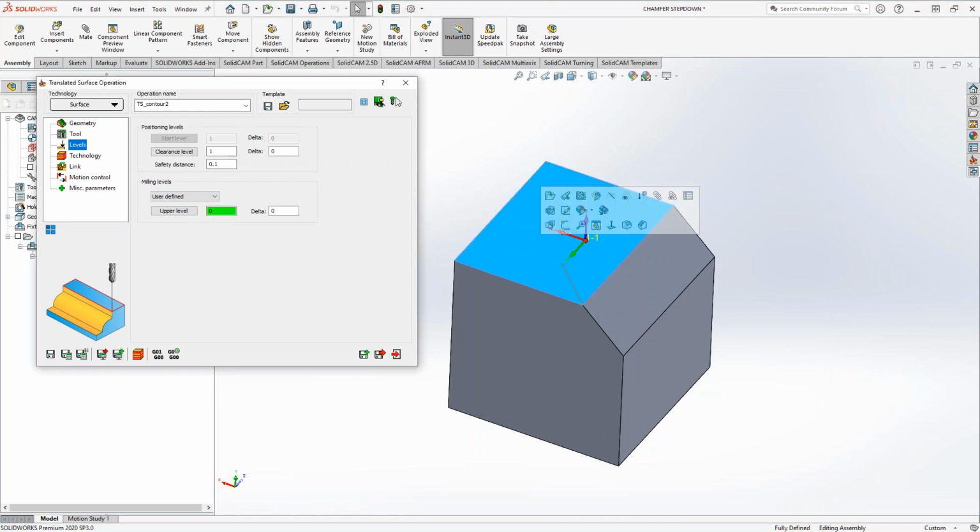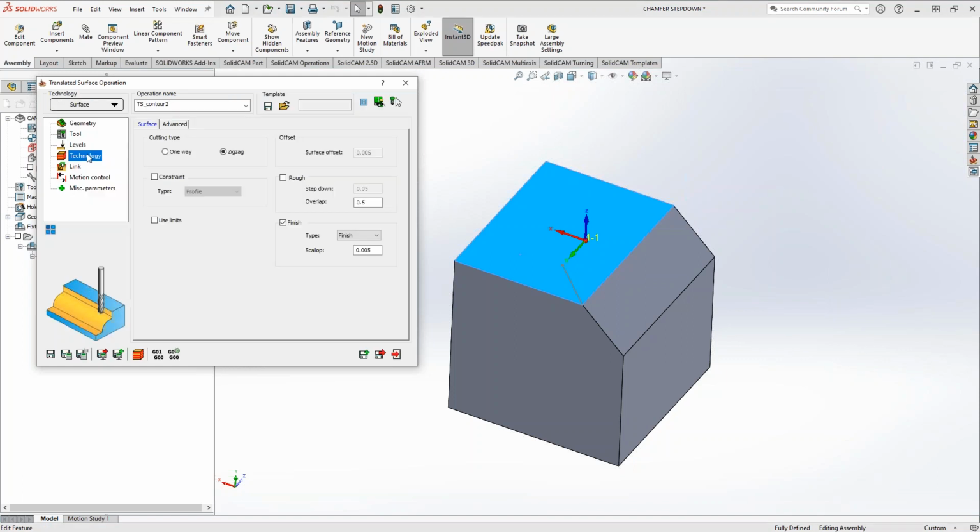So that's the top of the toolpath, but that's also going to relate to that reference point. So that can kind of give you some depth to work with. You'll see this with, I think it's the slotting toolpath as well, the distance that the chain is away. Again, to avoid confusion with this toolpath, just make sure everything lines up, and then you can have your upper level as just whatever plane those sketches are on. Technology, very bare bones, because again, what we're doing here is just very simple.